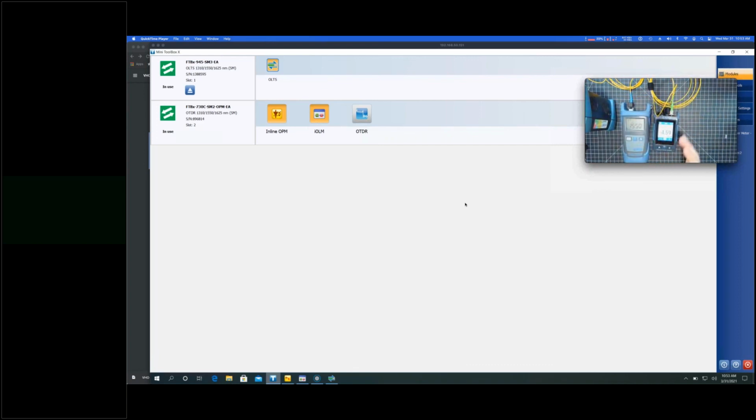That's because the 1550 wavelength is a longer wavelength and therefore cannot take this bend as easily as the 1310 wavelength. Therefore, I'm going to have more loss on 1550 than 1310, versus what we should have, which is more loss on 1310 than 1550. So that's basically what you're encountering. You may see that situation in a splice case or close to a connector, and you see both reflection and loss higher at 1550 versus 1310.